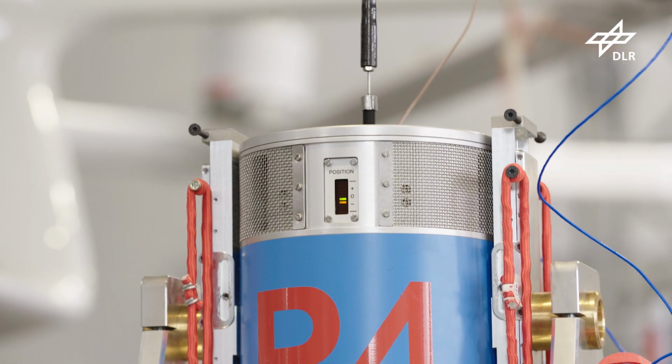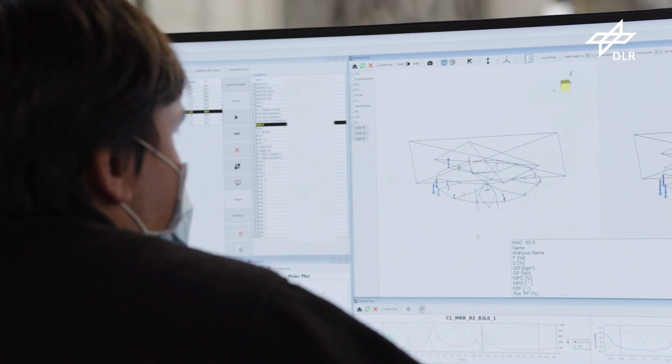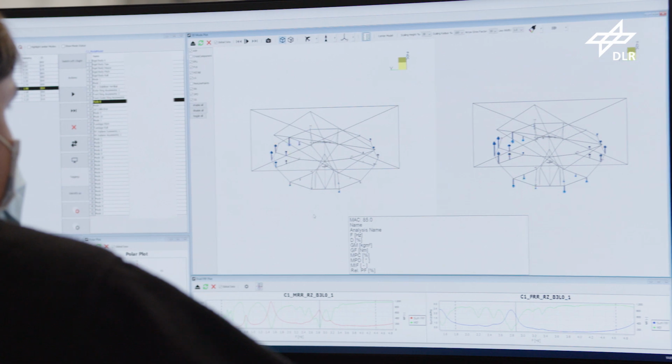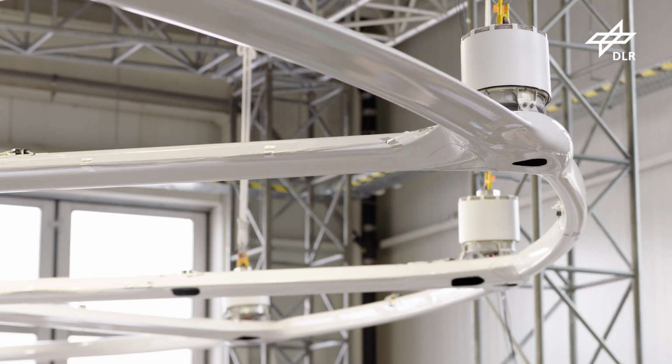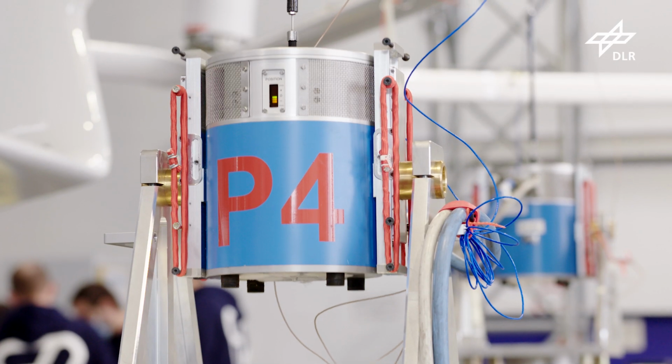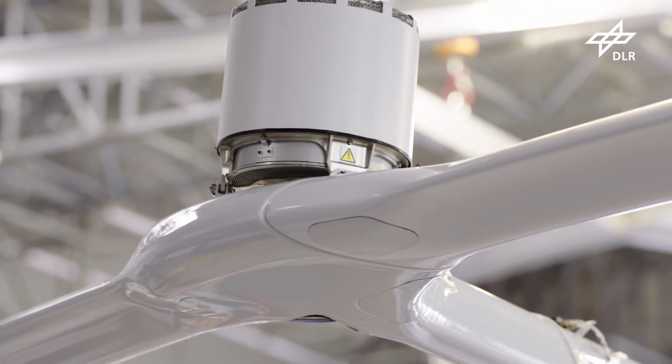In real flight, there are of course forces on the aircraft from things like gust loads or from the wind, and this can cause the aircraft to bend and to flex and to move in different ways. And we speak about mode shapes, so each structure, whether it's a tree or a pole or a human body or an aircraft, it has these so-called modes. And when we can collect enough of these modes together, we can build a model which represents the structure.